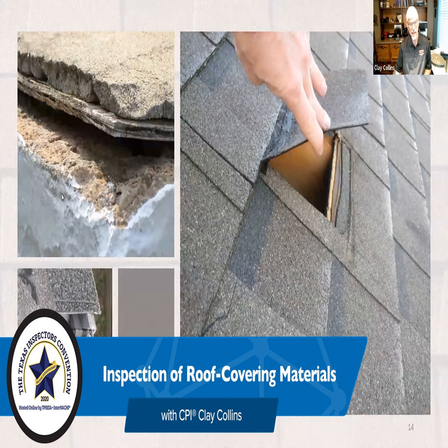Okay, now we're into flashing. Roof and wall intersections. We'll just say, here's a picture. I'm cognizant of our time. Here's our picture. You have all this, and flashing sometimes is not installed very well. Sometimes the nails withdraw, that's workmanship. Flashing's not installed and anchored. You have damaged roof boots, and we have the step flashing.